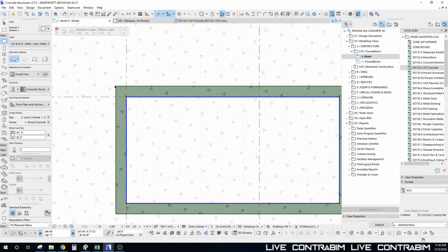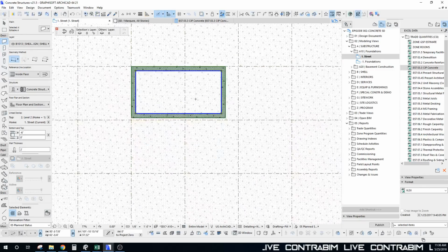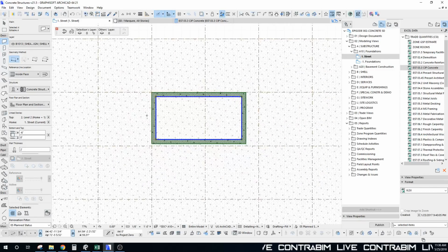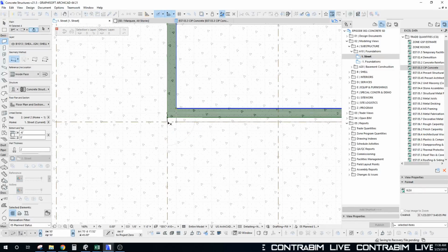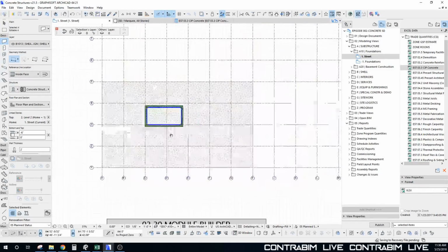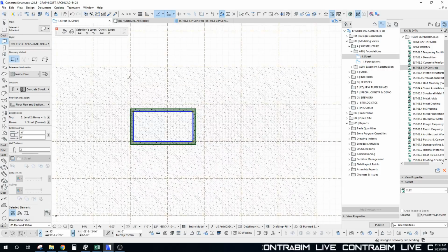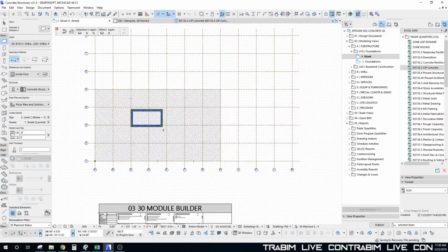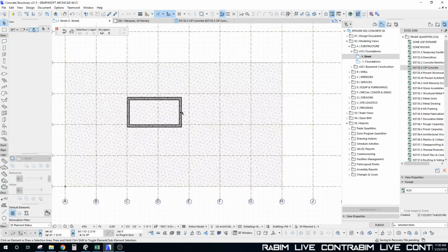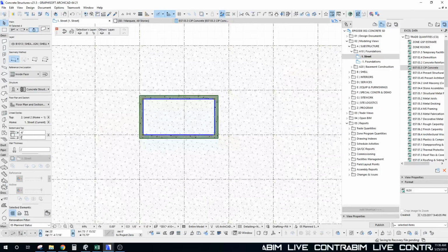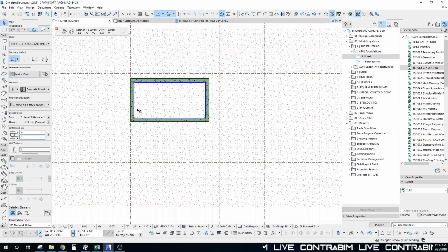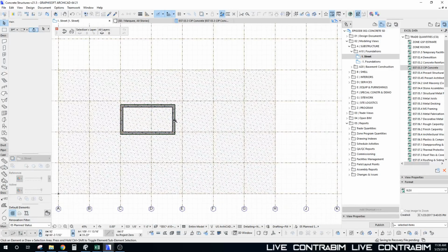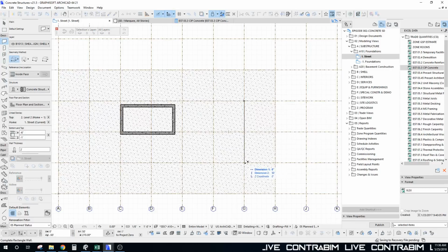But okay, so we can take this core now and snap it to any grid corner or modify it around and find the best placement for it in our project. And I guess that looks good. Decent bay depth on the one side, and then on the other side we can have 2 bays deep in terms of our column spacing. So that should work out just fine. And we're just going to take that bottom dimension and set that to -1 just to make sure that it is picked up, sitting on our mat foundation.